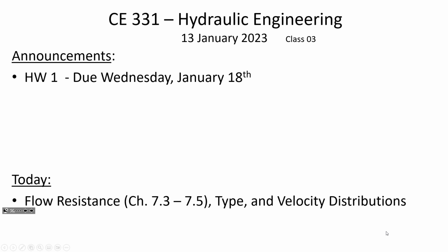All right. The conversion between PSI to pounds per square foot is just you multiply by 144 to get PSF. So if you have 1 pound per square inch, it's 12 by 12 inches on a square foot. And so if you have 1 pound on each of the inches, then that would mean on a square foot there's 144 pounds. So just a reminder about that conversion.